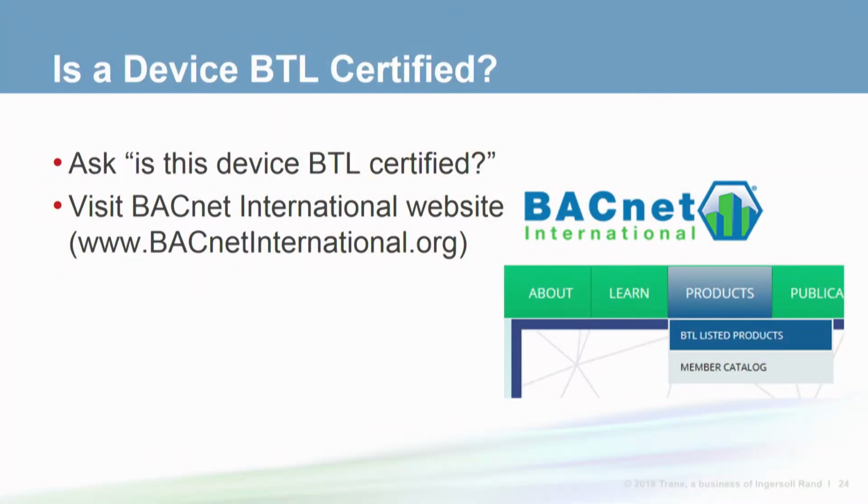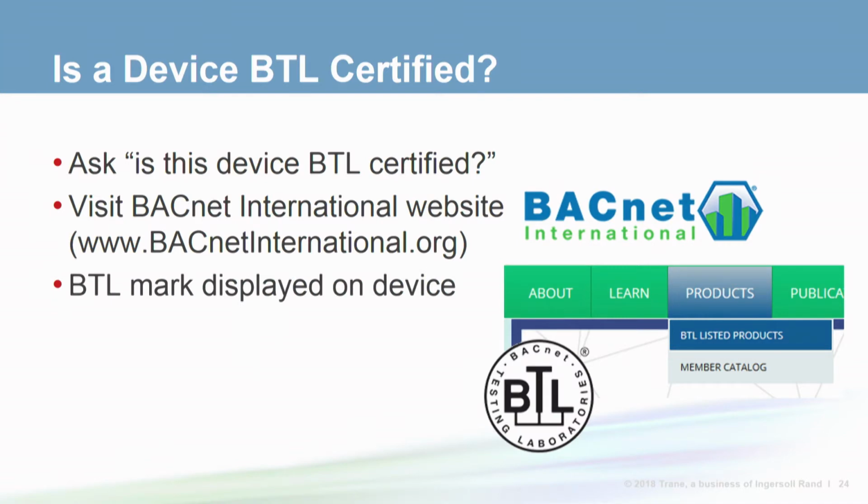This document contains detailed information about the object types supported and the building blocks, or BIBs, used to implement the functionality in this device. In addition to this listing, the vendor is authorized to display the BTL certification logo on its device, and it can use it in marketing literature. So BTL certification is important to ensure you get what you're expecting when it comes to BACnet.